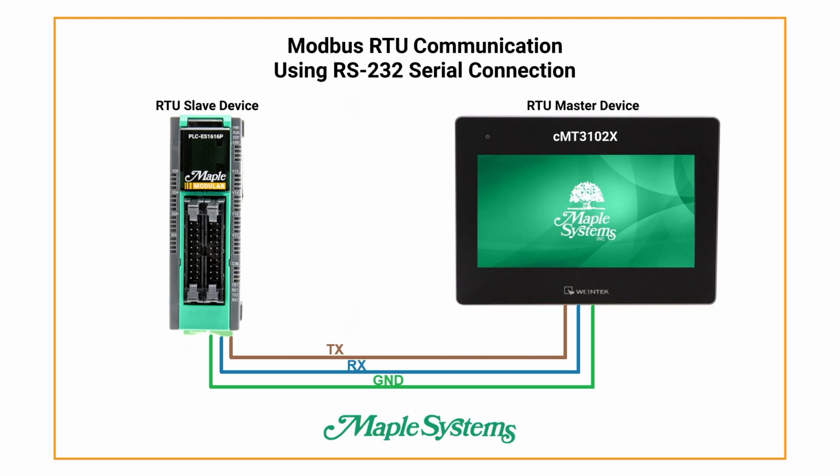Here is a diagram for connecting a PLC ES1616P Maple Modular PLC to a CMT 3102X HMI via Modbus RTU communication. Please keep in mind that you can also use any of the three Maple Micro PLCs. So you would connect the TX wire on the PLC to the TX wire on the HMI, connect the RX wire on the PLC to the RX wire on the HMI, and the ground wire on the PLC to the ground wire on the HMI.